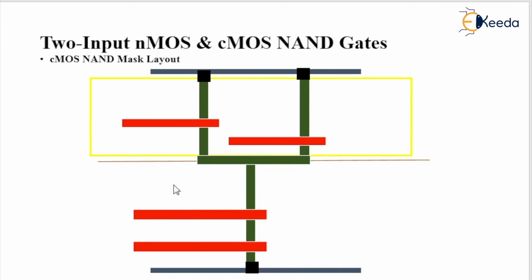Right. Not a resultant one yet. We will go through some patterns here. Up to now, 75% of the mask layout design was completed. So now I am going to repeat again here. This is our VDD and VSS metal supply rails represented with blue color, and this is P diffusion. Since it has a P plus mask, which is represented with yellow color, poly is crossing this diffusion.